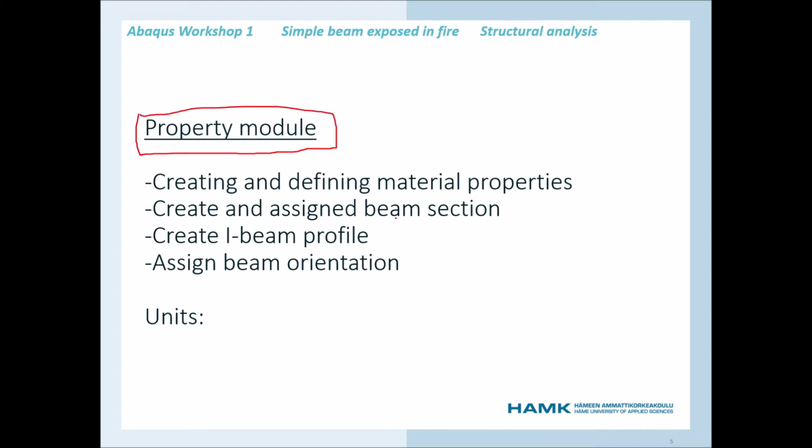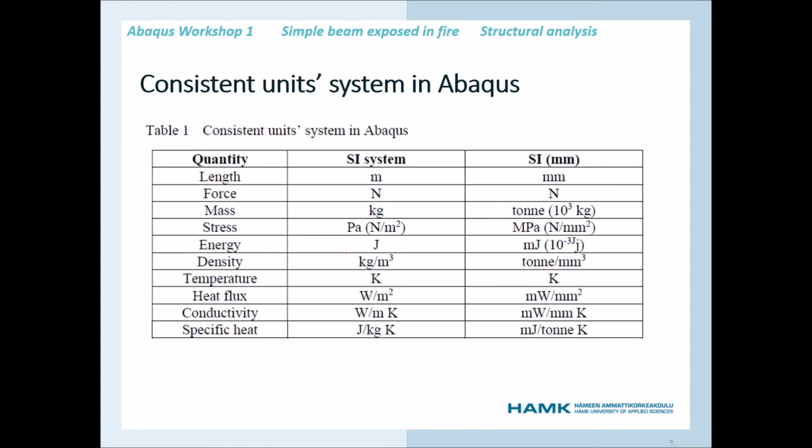For defining the material properties, we need to follow the units. In Abaqus, we don't have units, so we have to use a consistent unit system.